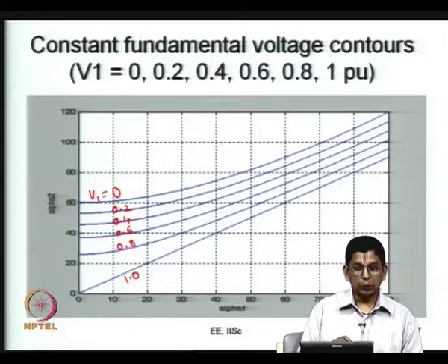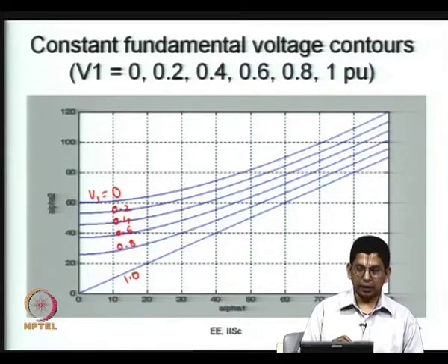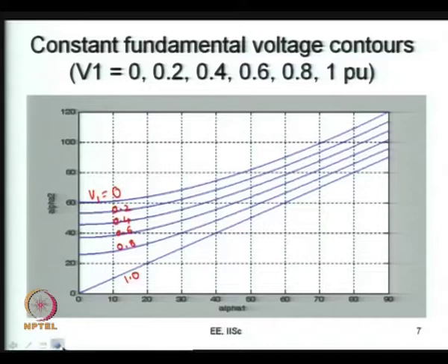So, which is the principal harmonic? The fifth harmonic would be the principal harmonic. In the 3-phase inverter, if there are any third harmonics in the pole voltages, they will get subtracted. VRO has some third harmonic, VYO will have the same third harmonic, and when you take VRO minus VYO for the line to line voltage, that effectively gets cancelled out.